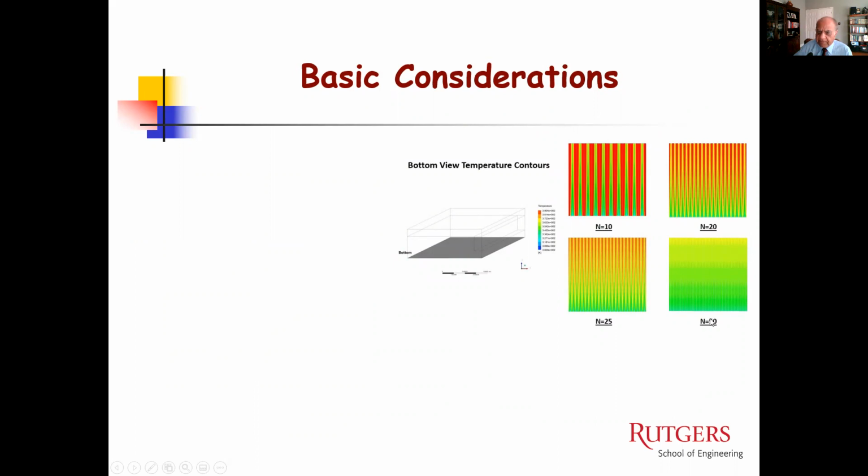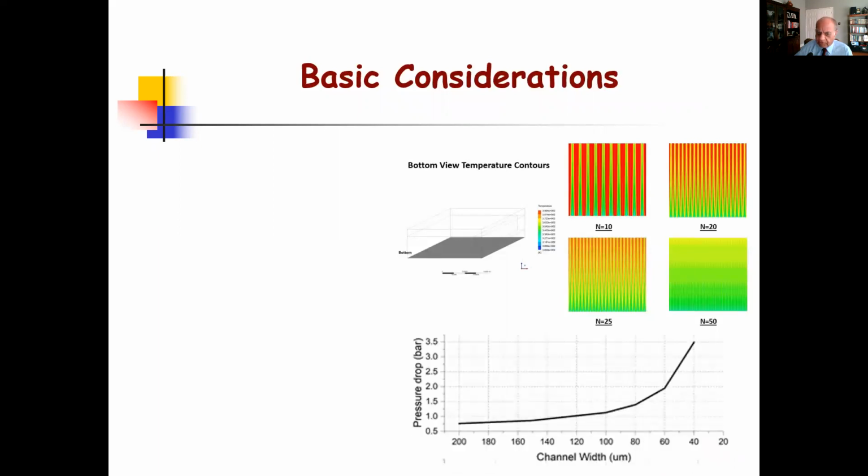These are just many microchannels, 10, 20, 25, 50 microchannels on a small area, which is about a centimeter by a centimeter. So the channels are basically of the order of 100 microns or less in most cases in width. They could be square, could be circular, and of course, there's a lot of conjugate heat transfer going on.